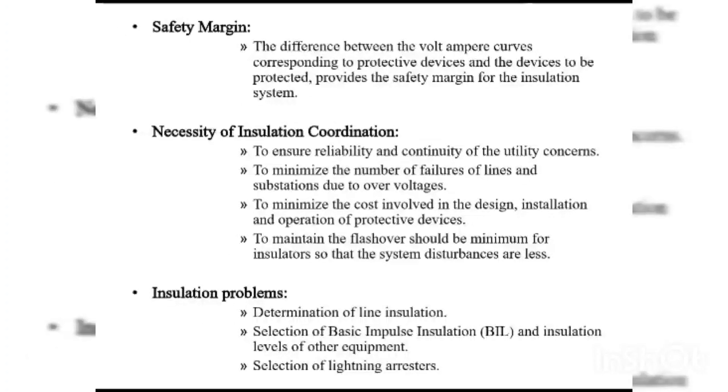Let's see the safety margin of insulation coordination. The difference between the voltage-time curves corresponding to the protective device and the device to be protected provides the safety margin for the insulation system.